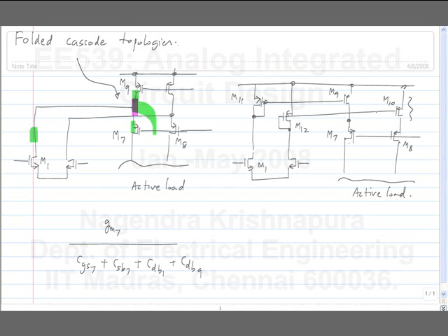What happens to the frequency response in this case? First of all, you have the parasitic pole here, because of this low pass filter. Current going from M9 through M7, part of it gets shunted through the parasitic capacitance. So there will be a pole gm7 by CGS7 plus CSB7 plus CDB9. Okay. What else? Is there something extra here?